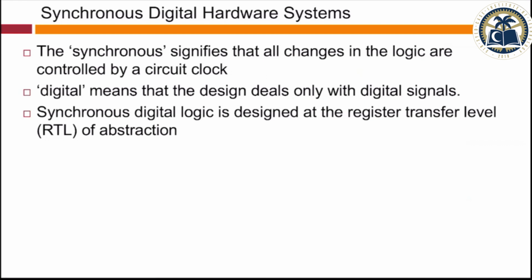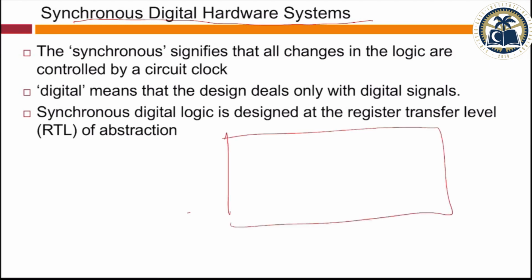That is number one. Okay, so this depends upon what type of application you are implementing. FS is important, the sampling rate or the data rate at which you have to process if you are real time or near real time.